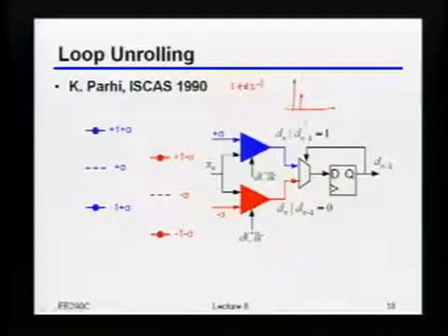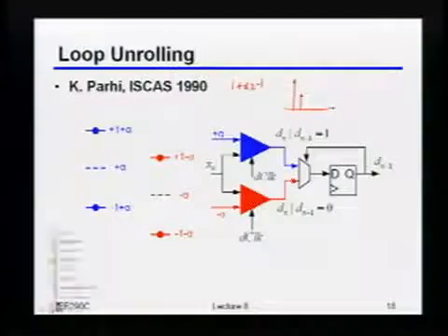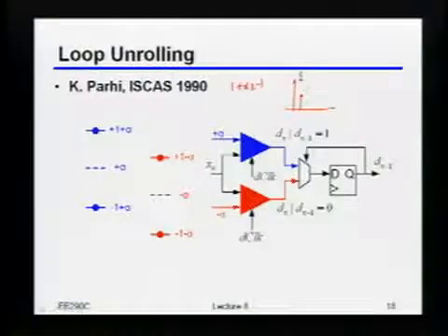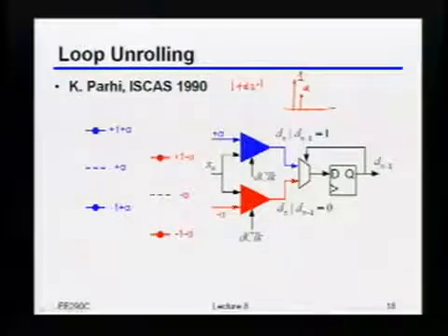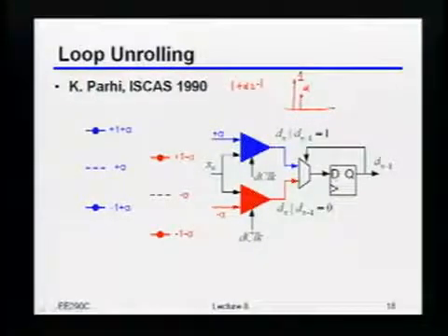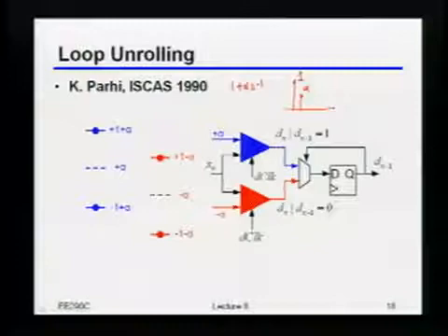that if you have a channel that looks like this, where the main tap is, again, just 1, and the second tap, or the post-cursor tap, is alpha, that's basically saying that there's 4 possible levels that you can get, right? Because even though my main thing is a plus minus 1, I'm always going to get a plus minus alpha from the previous bit, right? In other words, it's just saying that with 2 bits, there's 4 possible combinations you can get, okay?